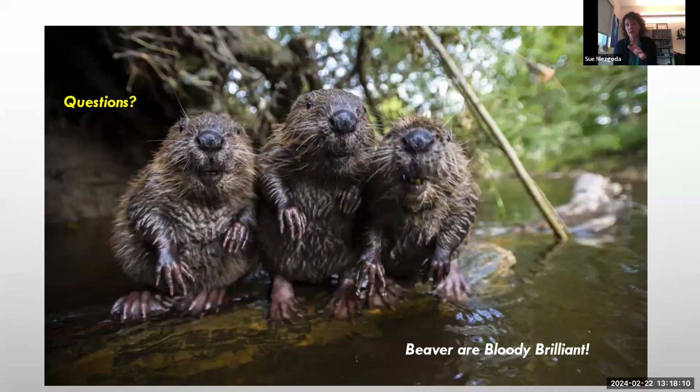And the water, they are somewhat impermeable no matter what, and so they don't act as a filter, but it's about creating the pond, right? That depositional environment that then reduces the phosphorus. And at the moment, we're not getting that ponding that we really want because of the scour underneath the weave material and the like. But the hope is that over time, if these continue to widen the channel, that will create deposition, right? And that with the phosphorus as well.